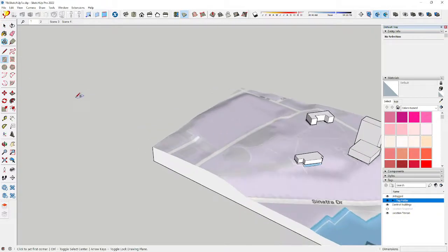I want to make one point here. The most basic technique in SketchUp that you need to understand, and you need to get to know these basic tools over here. There are lots of keyboard shortcuts that are really helpful to use. Anyway, if I'm going to make a rectangle, let's say, and I want to make a little building by just pushing up on it, P is the shortcut for push. Now I've got this little building that I could bring in as context.